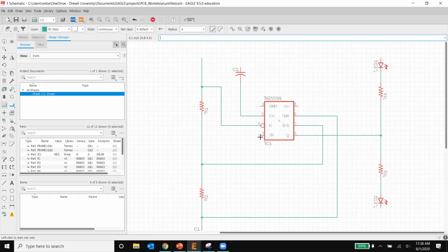Now pin number 2 is gonna connect here. Now if you notice, you're gonna say these two lines here cross, but it's exactly what I said before. If you don't have this junction point, then there's no connection, so you are safe. Don't worry about crossing lines. I mean, all right, it's a bit tedious. I could have drawn this better, but whatever. I'm gonna fix it later on my board layout. It's a simple enough circuit so I can understand it.